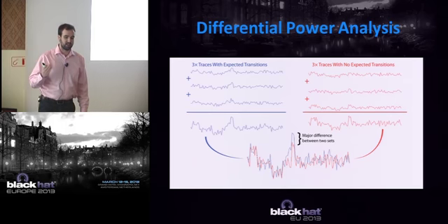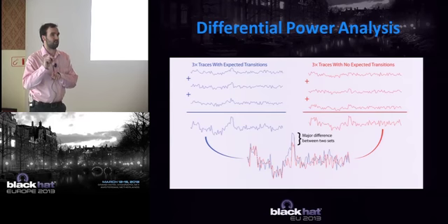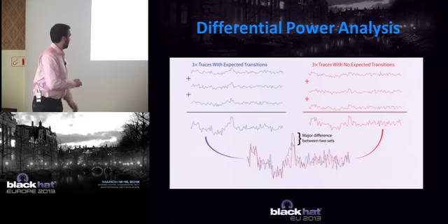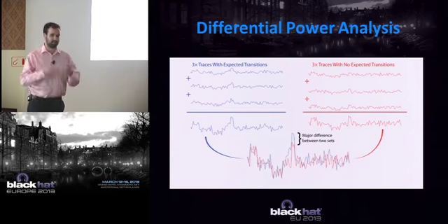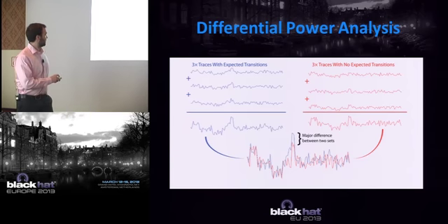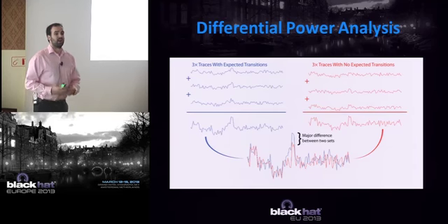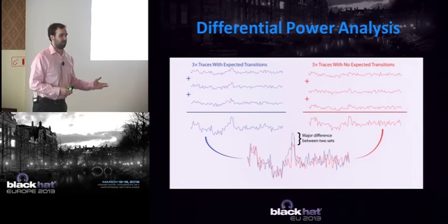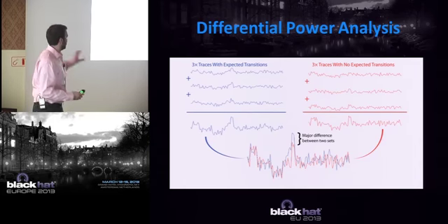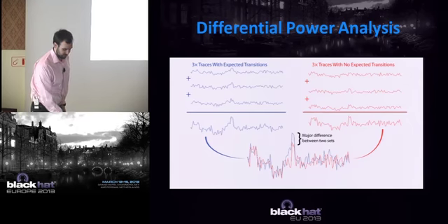At another point, that single bit was always 1, if I was right. And when I compare the average, or add up all of those sets I've made, I should see this difference like that. If I was wrong, and assuming you have a lot of traces, not just 7, it should just average out to 0.5, and the rest of the bits should also average out to 0.5. So this is how we do the original differential power analysis.